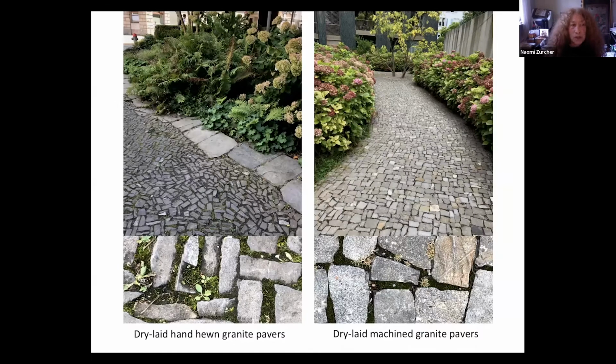While the application of paving always reduces the organic layer, the fact that there is gas exchange and water infiltration can support a viable root system, which will, through life cycle processes, contribute fine root exudation of carbon compounds and senesced and decomposing root tissue to the soil. The dry laid technique also allows for easy adjustment to manage disturbance.